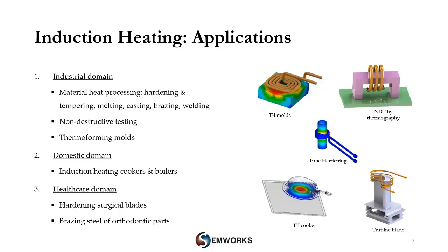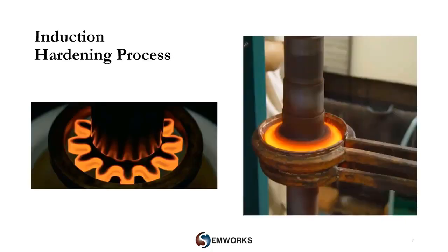On the right, as you can see, are some of the applications of induction heating which we're investigating using EMS for SOLIDWORKS. We have the induction heating molds, the non-destructive testing for crack detection by thermography, the induction heating cooker, the preheating for turbine blades, and also hardening steel tubes, etc. For today's webinar, we inspect this last application, induction hardening, since it is one of the main industrial applications for surface material treatment.